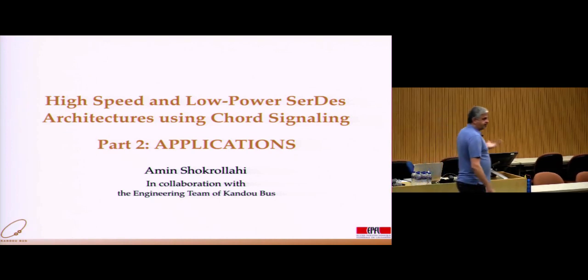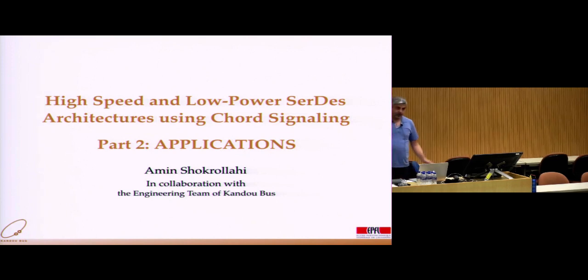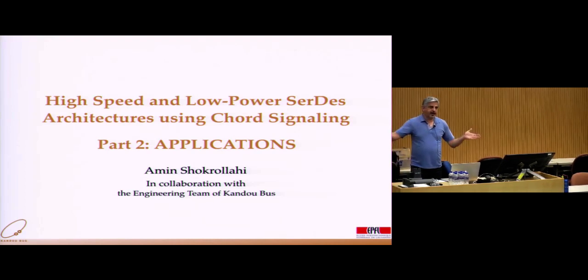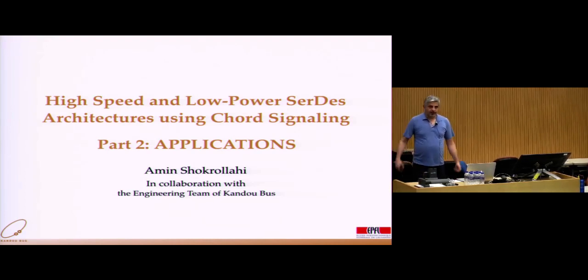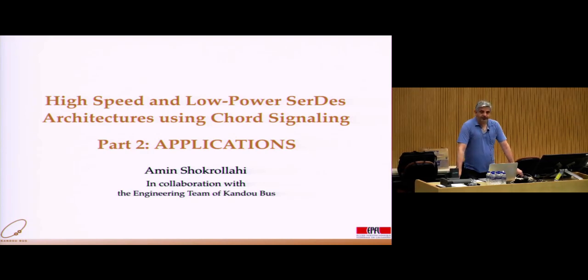And the coding we are using is not really an error correcting code. It's really a modulation scheme, right? So you want to make the modulation scheme as resilient to noise as possible. And then you may want to use an outer code, which is digital. We actually do that also in our systems. Because if you get a bit error rate of 1e-9, generally in systems you want 1e-20. So if we get 1e-9, then with a very lightweight code, we can bring it down to 1e-20. We could also do 1e-20 by design, but that means much more cost because you need to over-design your system.